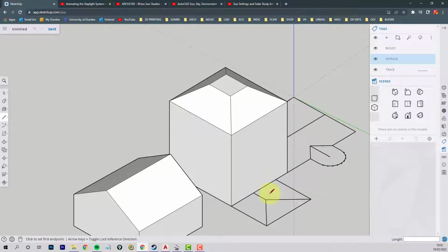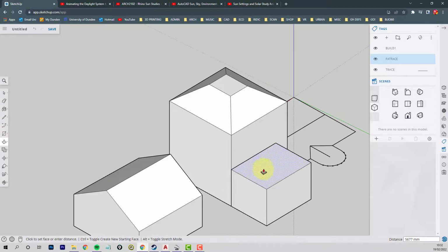Now the back is a little bit trickier because we don't know where this is going to hit the wall. We need to do a bit of drawing to establish that. Okay, so let's get the kind of footprint in first. So we just need 3 lines, tabbing it Alt again just to stop it jumping onto the underlying grid. So we said 6,000 for this one.